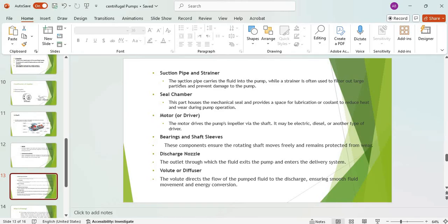Yeah, for the suction line, there should be a strainer, in case the fluid has particles. If these particles go inside the suction line, they are going to start collapsing the blades of the impeller. So in order to avoid this, you should have a strainer collecting every particle in the inlet line.